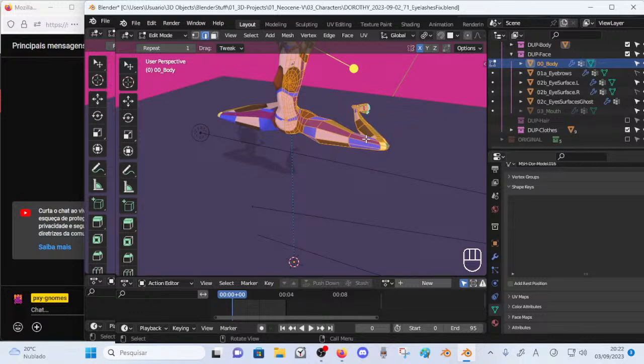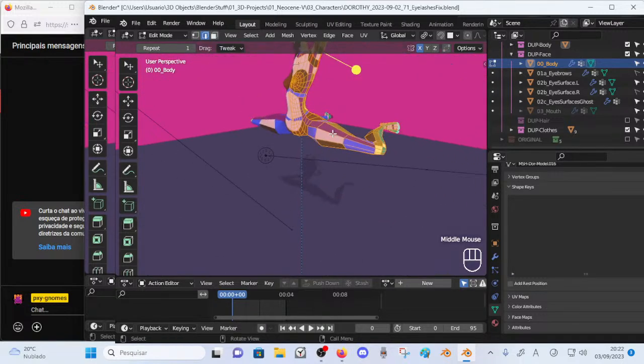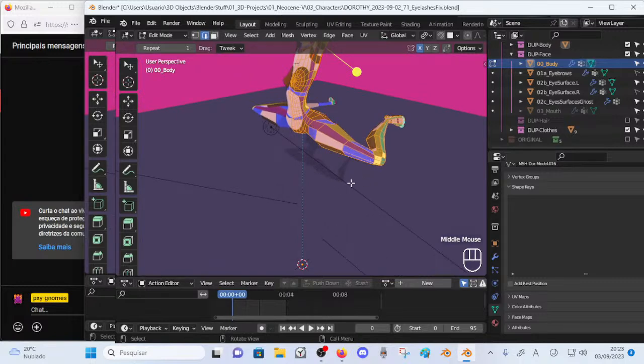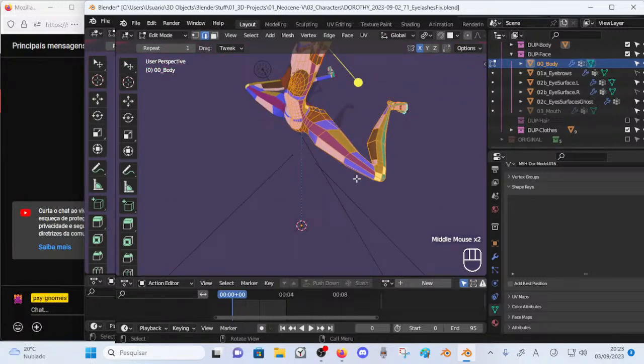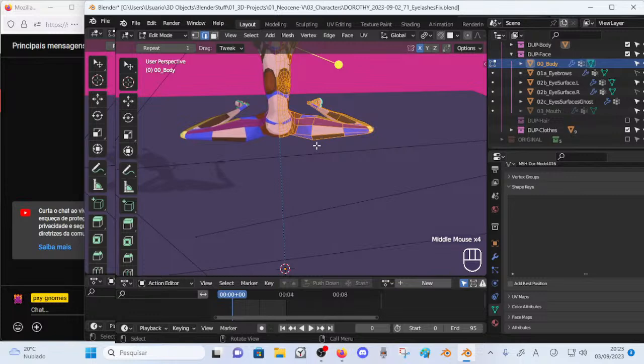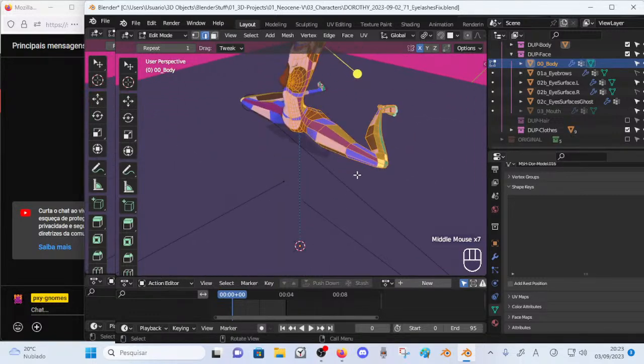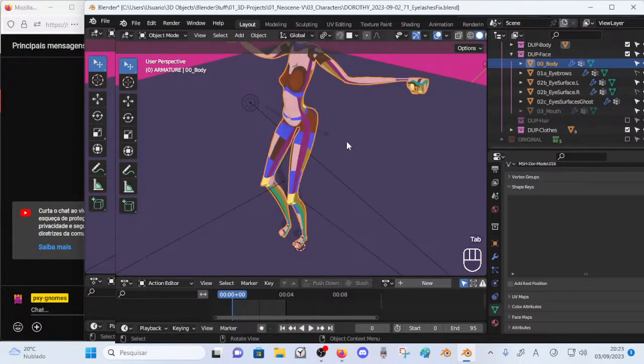So currently, because there's only one rest position possible, we can only deform from one spatial reference for the mesh. So as it rotates further away from its original position, we start to have huge, terrible deforms, artifacts, right?